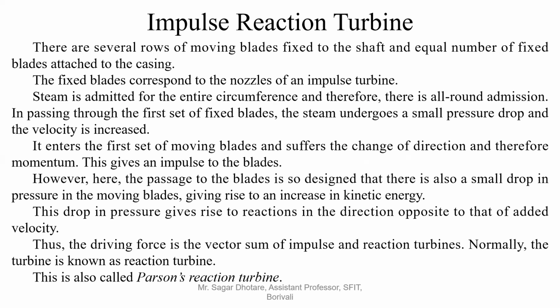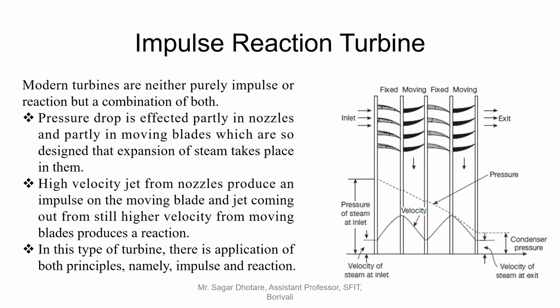The shaft always carries the moving blades and the casing always carries the fixed blades. Okay, so based on the number of fixed blades, the nozzles are to be designed.